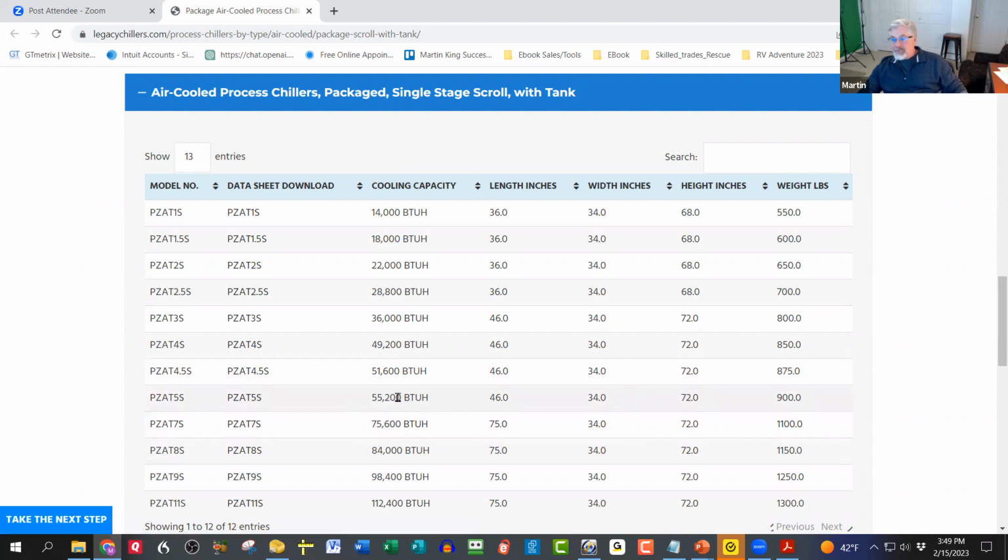But if you jack that up to 60, you're going to get close to, I'm guessing now, 80,000 out of that same chiller, right? And vice versa. So any number off of that can cause a change. That's probably the main reason why I wanted to show this to you. Usually in the specifications somewhere on the capacity tables, it'll tell you that. But that's a really, really important thing to understand. We have a few customers that screwed that up.